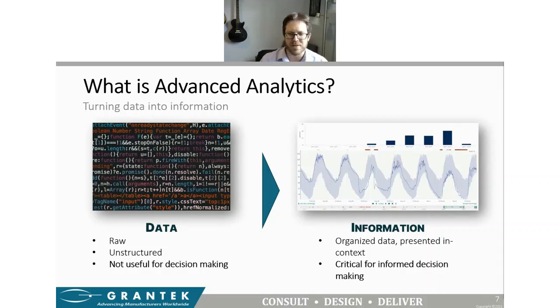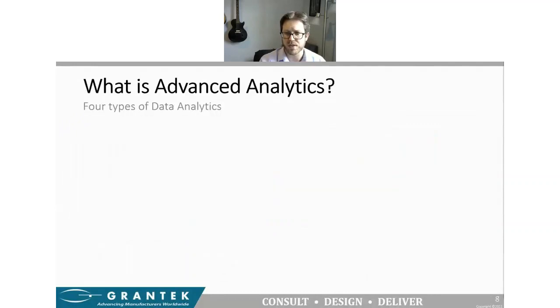62 is just a number. 62 degrees Fahrenheit is better, it's a temperature. But you're at 62 degrees Fahrenheit now, but at risk of going over 65 degrees, and therefore you're out of control limits and you need to send an operator over to station C to check things out within the next 30 minutes. That's a lot more information with very specific instruction on how to react. And you can see where something like that is very valuable in your manufacturing and controls settings.